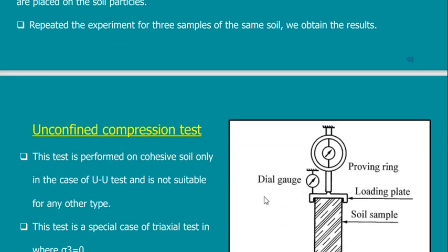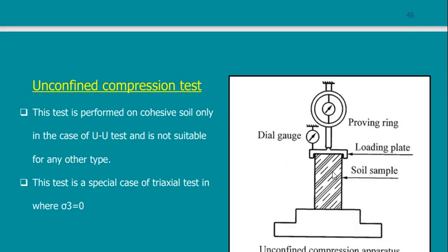There is another similar test. You are going to use a similar one in your concrete lab. In concrete lab, you are going to take a sample, put it in a piston, and it will be loaded till failure. In my triaxial test, I can simulate this. How? I will put the sample, but I will not put anything around the sample. Water is not going to be put. And I will just put the piston.